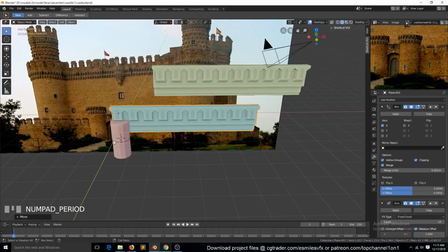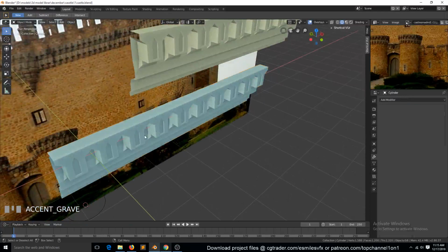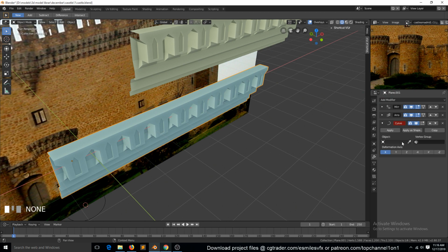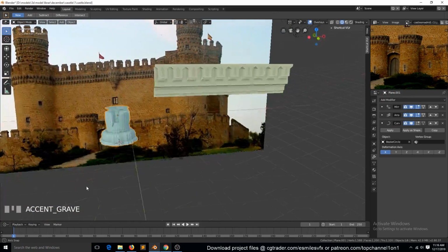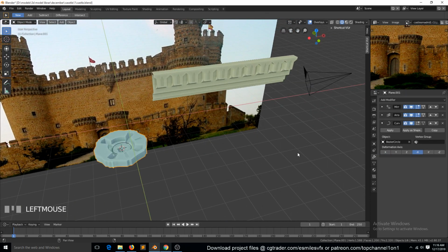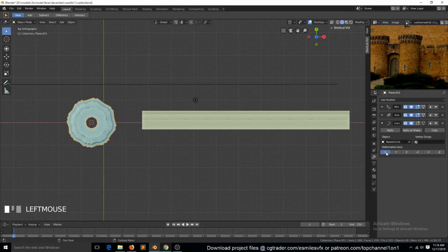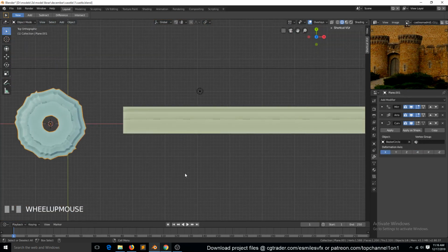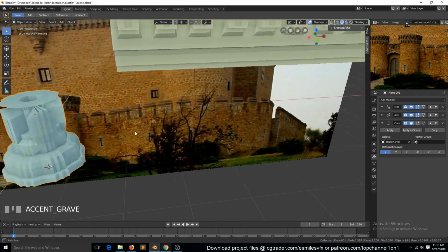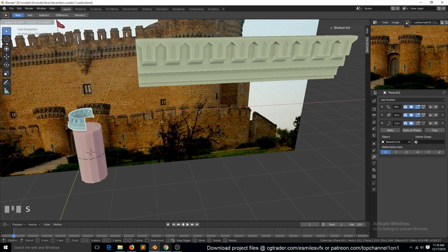Move it up a bit, and then let's first hide this. Then we can add a curve deformer. Select this curve as our deform object. Let's try changing the axis to -y and see how that works. Okay, let's change it back, and then let's scale this down a bit, because you see, let's also unhide this tower. Scale this.